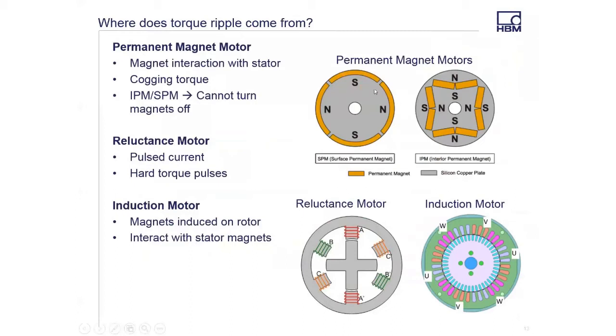That's going to be spinning around the rotor. Now, if you've ever walked up to a permanent magnet machine and tried to spin the shaft when it wasn't connected to anything, you'll notice that there are these bumps you overcome. And when you're overcoming these bumps, you're actually pushing the magnet through the stator slots, because the stator's construction is a big chunk of iron, and the magnets want to attract to that iron. So you have to overcome this.